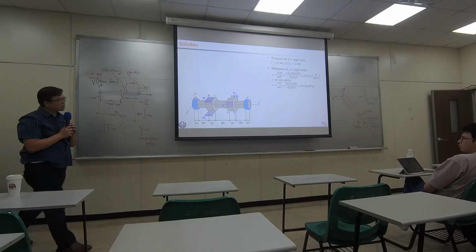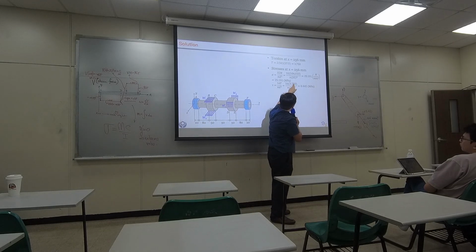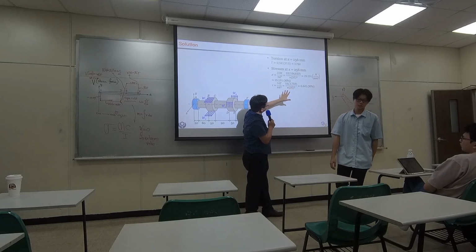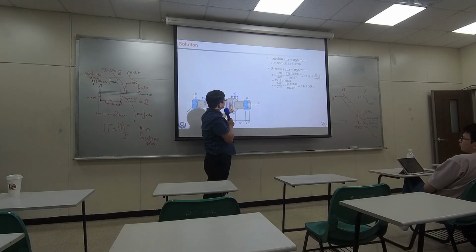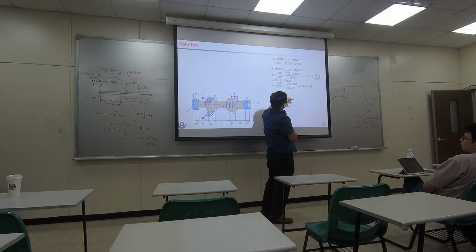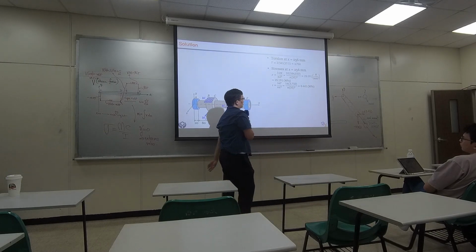So I use the torque. You can compute the torque right there, the same amount, and use the same equation. So at the end, at the worst case position, you have 25 megapascals in normal stress and 0.4 megapascals in shear stress.